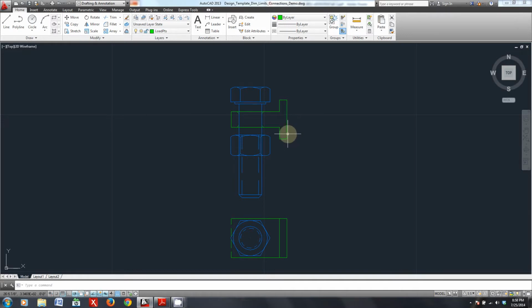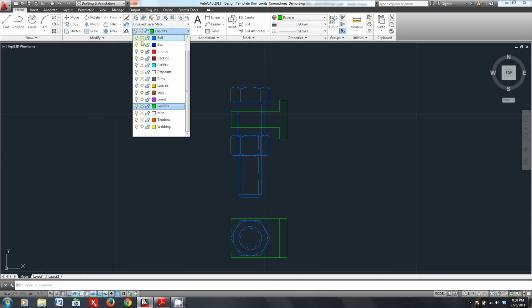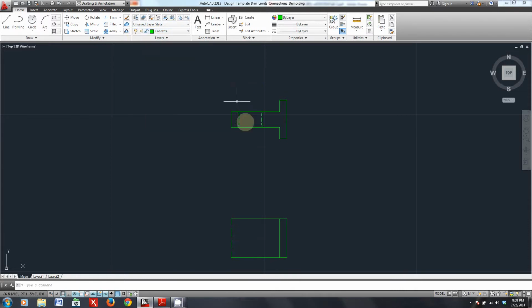Now, the main components you can see are this region here that juts out, and that's basically where you have a hole that drills through. I'll unhighlight my box here so you can see. Looking through here, I have the dashed lines to represent where the hole will go through the main male part, and then I have these little details just to show where I might chamfer these edges with, say, one of those conical shaped deburring tools. So I've included a chamfer of about maybe 1/32. I don't know, it's just a guess. Really, right now I'm just trying to get out some ideas.